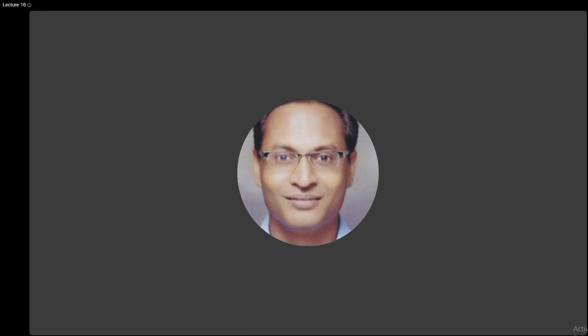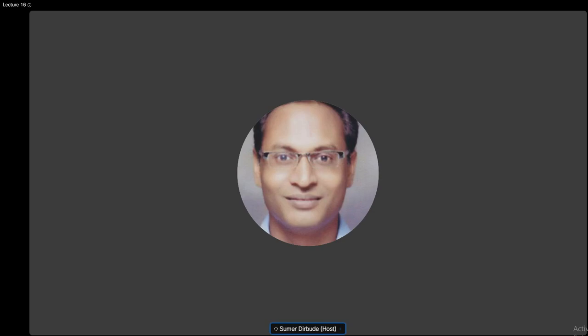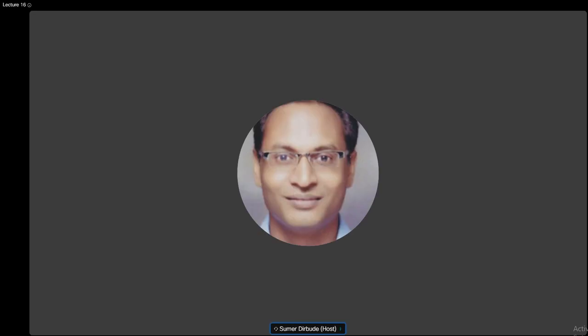Because first I gave 0.12 mm, and then 0.21 mm element size, so I was able to get the deviation on the right hand side. There was some little deviation. As I decreased the element size, the deviation was large. Decreasing the delta x doesn't mean that you will always get convergence, I mean, good results. Why? Because once you decrease the delta x, your round-off error starts increasing, isn't it?